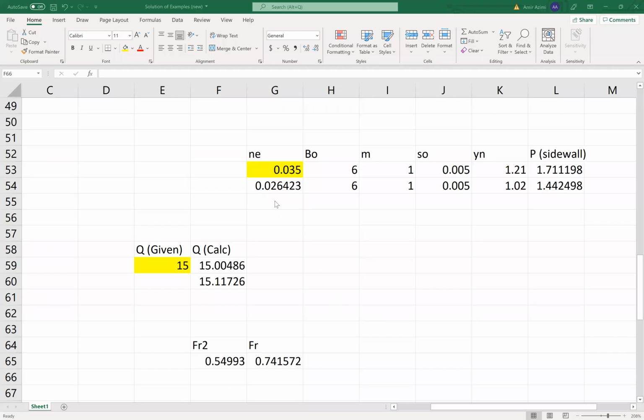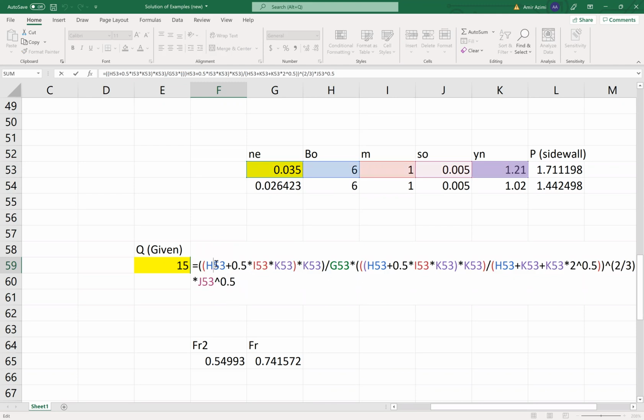So we'll go to Excel. And then here we start the equivalent Manning constant as 0.035. We use the rock cut value. The bottom width is 6 meters. Sidewall slope is 1. Longitudinal slope is 0.01. And then here, discharge is 15. And on the right-hand side, I calculate the area.